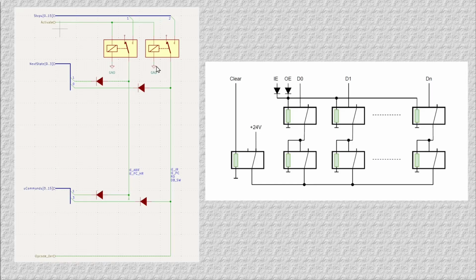And for example, an operation command, which you see here, consists of 2 of these cycles. In the first cycle, the address bus register is written and the program counter help register is written. In the second cycle, we write the new opcode of the next command into the instruction register.